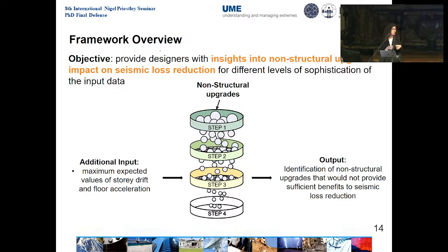But right now, the tool has access to the FEMA P58 methodology database. So if you want to select other fragility or consequence functions for the methodology, you can do it. But if you want to assume more specific fragility functions based on other considerations, you will need to modify the parameters of the fragility in order to apply.